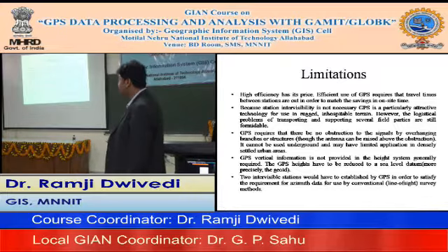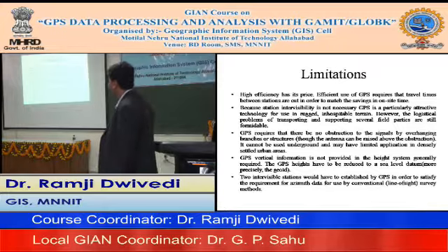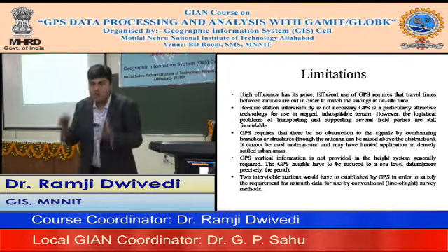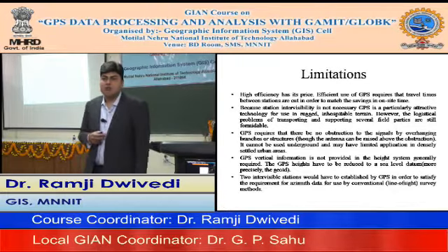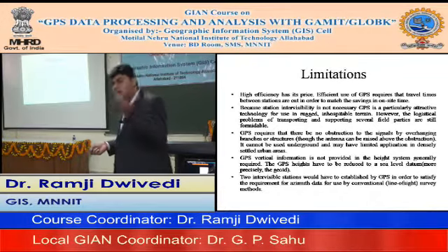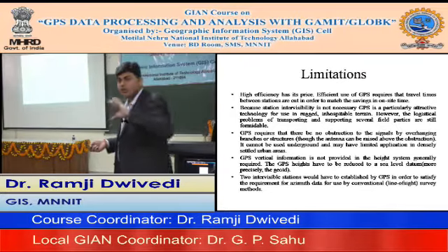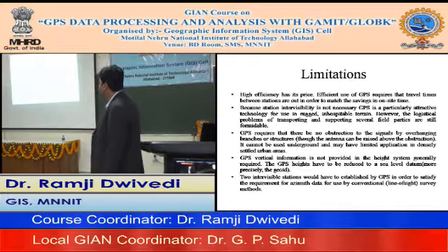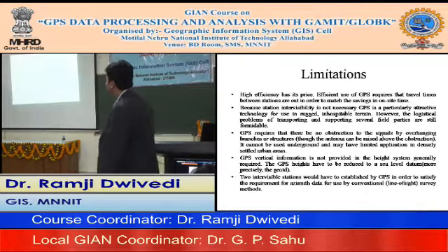Obviously, one issue whenever we read the literature on GPS is that vertical information is not provided in the height system generally required. We are more prone to use the height system of local mean sea level or the local geoid, but GPS provides height with respect to the ellipsoid. Are you aware of the geoid model? You can convert between these two systems. Today, people are expected to use it for a variety of applications.